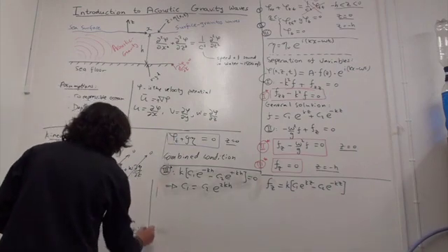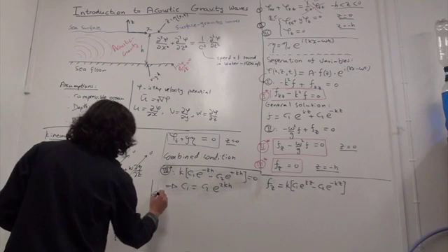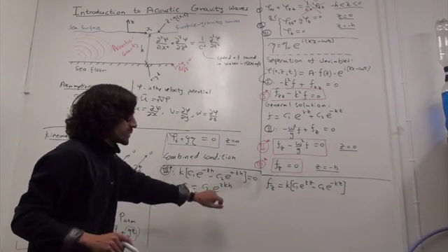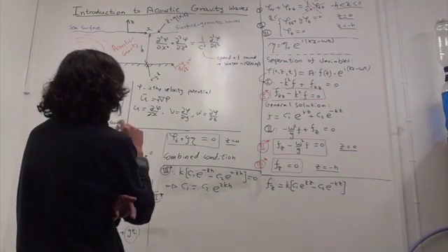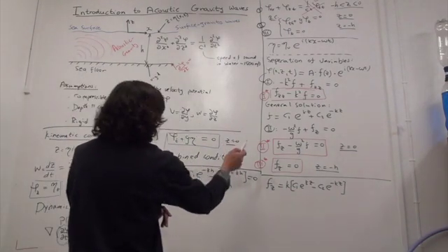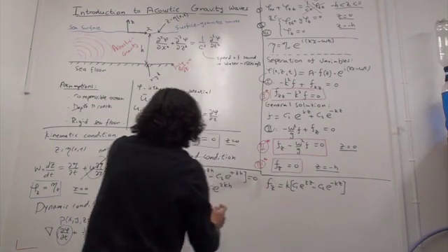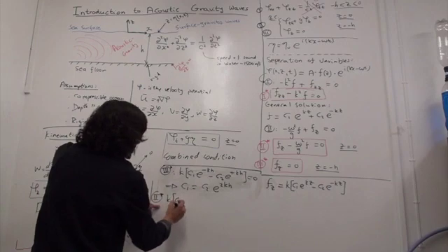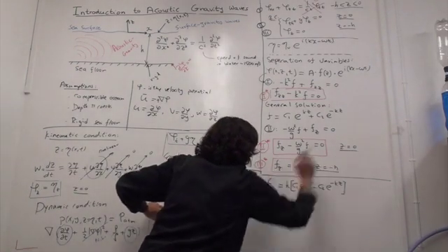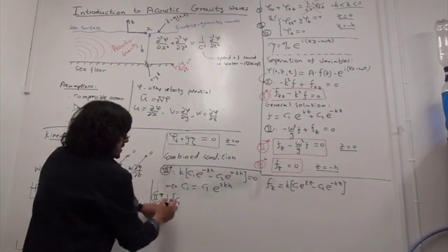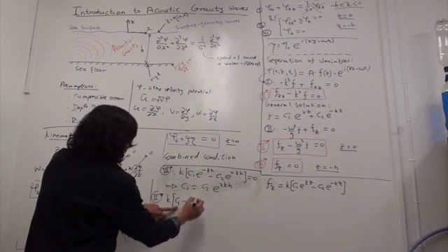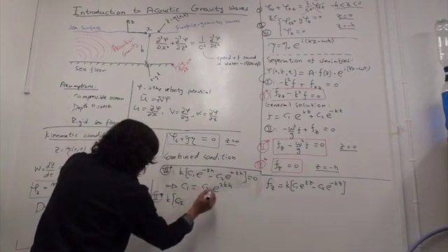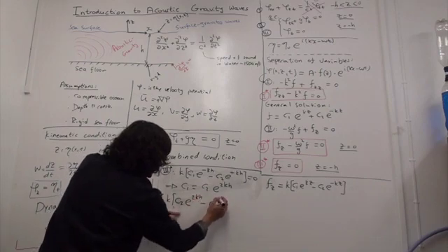Okay, now we go to the second boundary condition, 2 star. We do the same thing, we substitute there, but now we know that c1 is c2 e to the power 2kh. So we can already substitute that as well. So now we're looking at f_z, I wrote the f_z here, the general one. So we're going to have f_z, which is k times c1. Now we're looking at z equals 0. So this is 1 and this is 1. So c1 minus c2. I'm going to already substitute what is c1 here. So we have c2 e to the power 2kh minus c2,